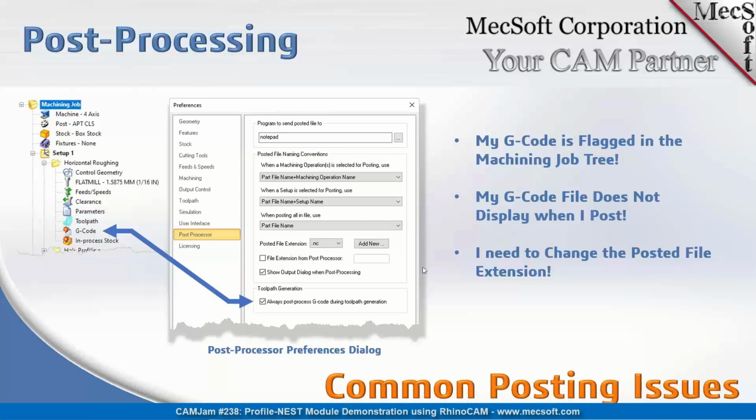So also here, the third item, I need to change the posted file extension. By default, it comes as .nc. Your controller may require a different file extension. It may be a dot something else, whatever your extension is.